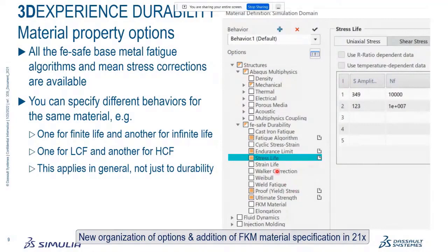And here you can, for example, put in your SN curve, right, under stress life. So this is being shown here in MPa, but actually our default is pascals or newtons per square meter, so they probably should be a E8 on those.